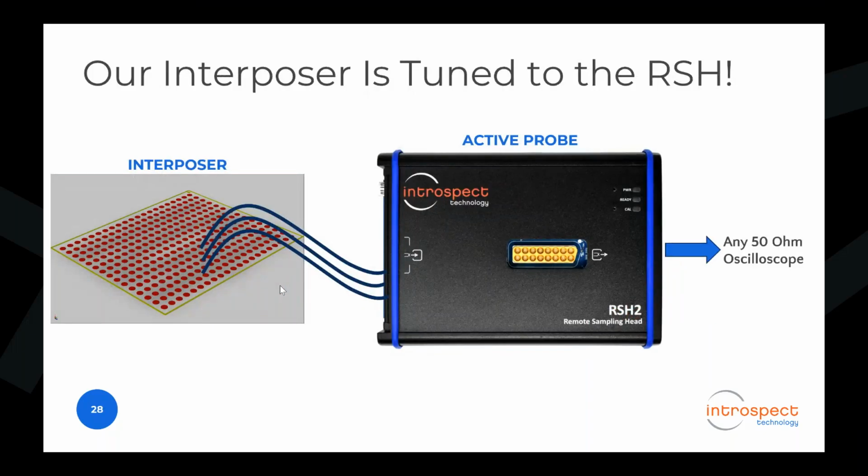So at Introspect, we decided to take a different approach. What we really did, in a nutshell, is make the interposer part of the probe amplifier. If you remember my animation from before, where you had the cable going to the tip, now we're saying that the interposer itself is the tip of the probe amplifier, a multi-channel tip. This means the tip resistors, where the cables actually tap the signal under test, go under the BGA array itself and not on the periphery of the BGA, and that eliminates the few millimeters of stub that I just showed you earlier.